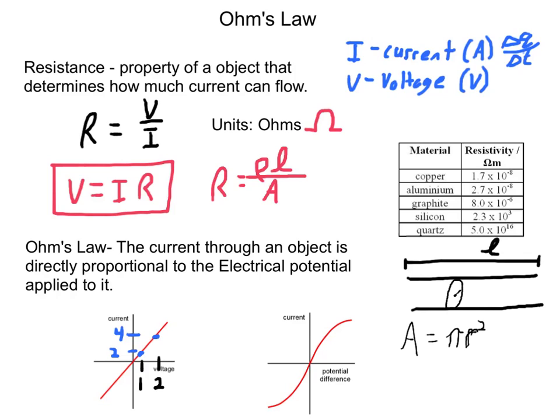That's Ohm's law. Now, not everything is ohmic, meaning that it follows Ohm's law. Some things don't. This would be a very nice resistor that perfectly follows Ohm's law. This would be a graph of maybe a filament lamp, aka a regular incandescent light bulb, the thing that was just outlawed by the government here recently in 2014. They are all being phased out now, that has a little filament that glows white hot inside of it. A filament light bulb has a portion that follows Ohm's law very nicely. In fact, the portion between those two lines is pretty much a straight line.